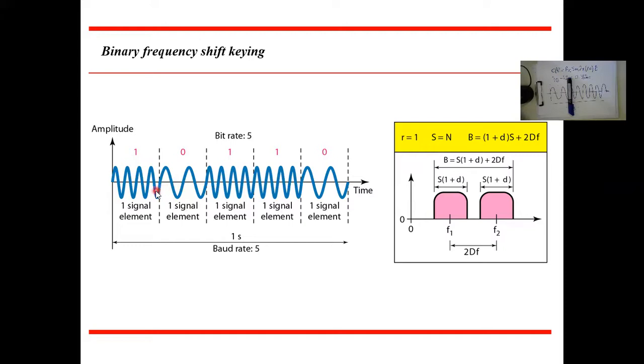So we have what's called a smooth handover at this point, because a cycle is terminated and a new cycle starts. However, in the case of non-coherent frequency shift keying, you will have what we called previously the phase overlapping at the transition points between bits, because you don't have a complete number of cycles.